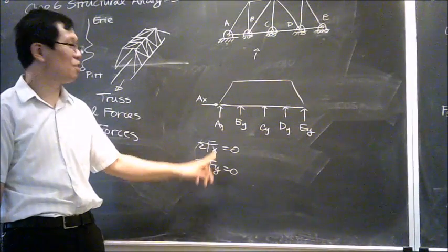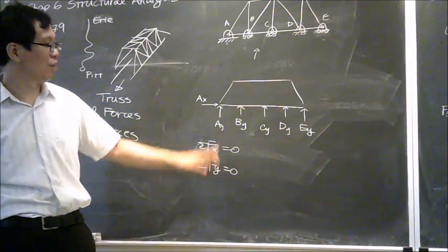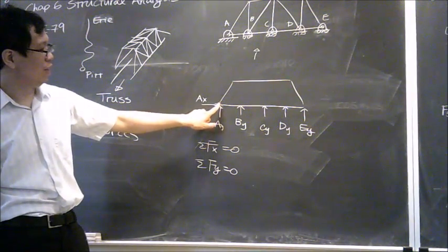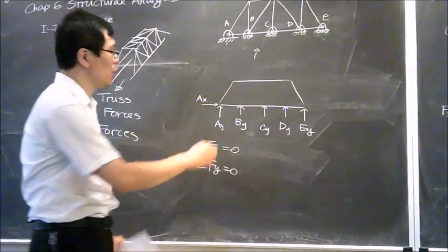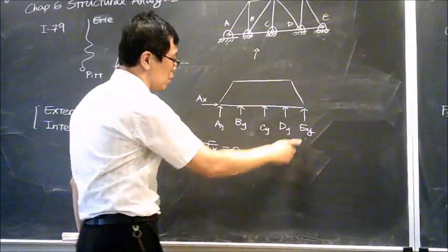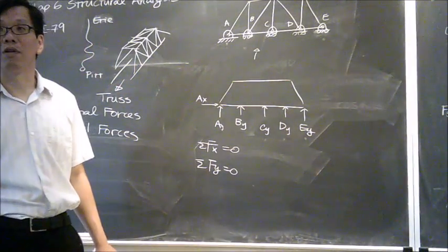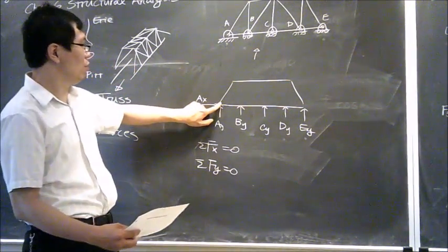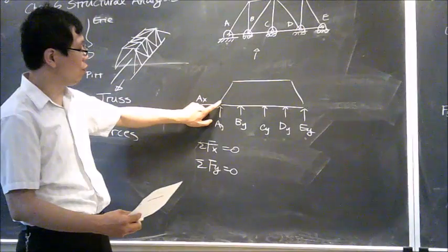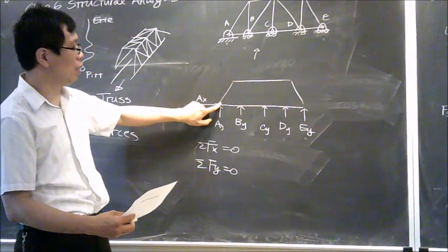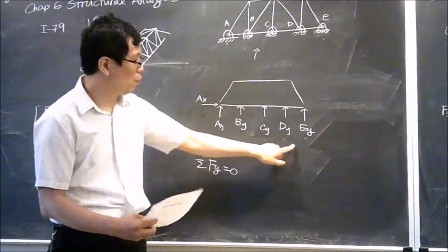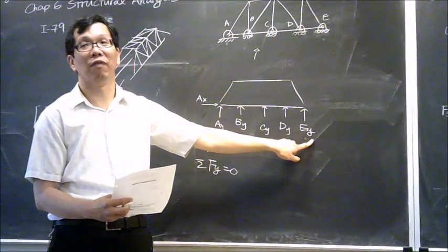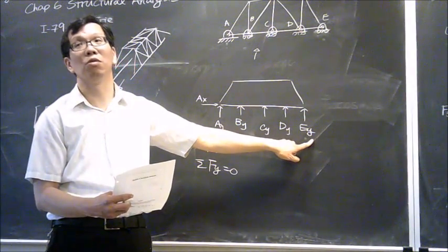Obviously not, right? So you might need to take a few moment centers. For instance, over here, then take this one. Of course, we know Ay plus By plus Dy plus Ey equals 0. And you also know this is not going to be rotated. So if you put your moment center over here, those two forces with a specific combination are going to equal 0.